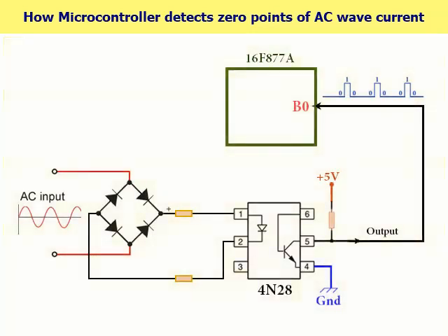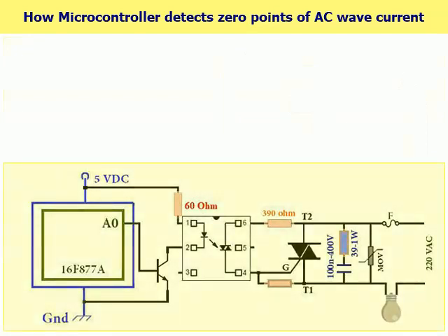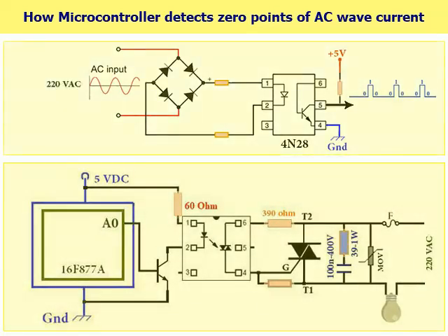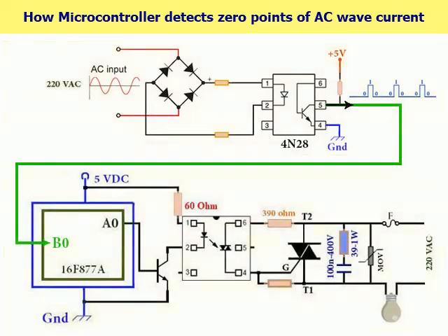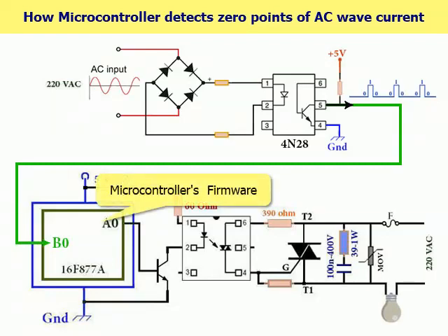Let us modify the previous TRIAC driving circuit by adding the zero cross detection circuit. This is the final form of the electronic circuit diagram used to control the power of the electrical devices. All we need now is to program the microcontroller with the appropriate code, through which we can control the timing of the triacs triggering in each half wave, which means controlling the operating time of the device within each half wave, and thus controlling the device's power.